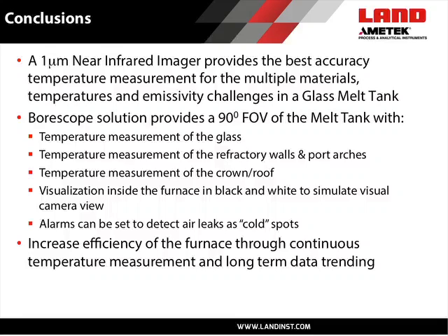So it gives you very good measurements of the glass itself, of the critical refractory materials, and also gives you a visualization of what is happening within the tank so that you can detect trends, see flame patterns, detect cold air infiltration that might be caused by a crack in the structure. NIR-B allows you to increase efficiency of the furnace through its continuous temperature measurement and long-term data trending functions.